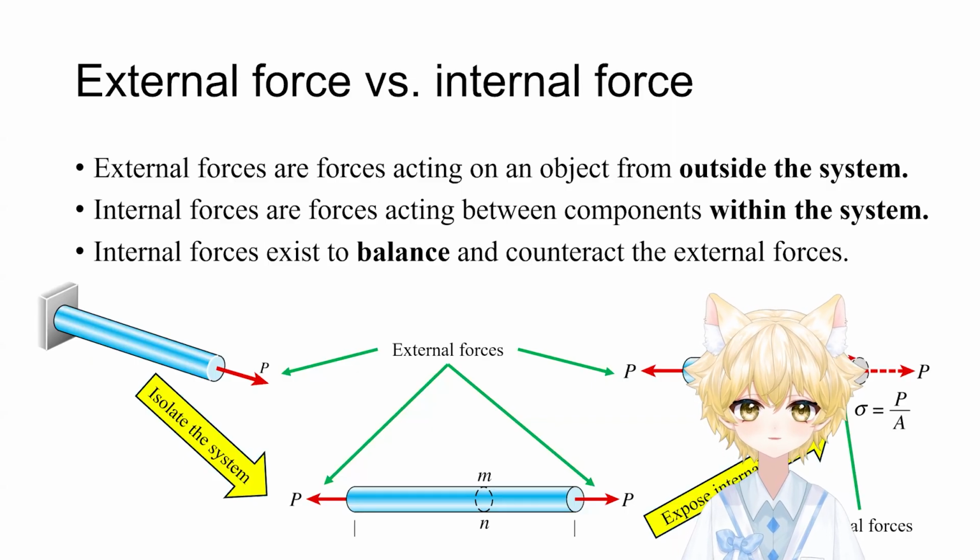Here is a crucial part for solving problems. You cannot say internal force until you make a cut, right? Look at the diagram. We start with the whole bar. Always say there is an external force P, right? To analyze the stress, we have to imagine a slicing, right? Imagine an imaginary cut from MN, right?